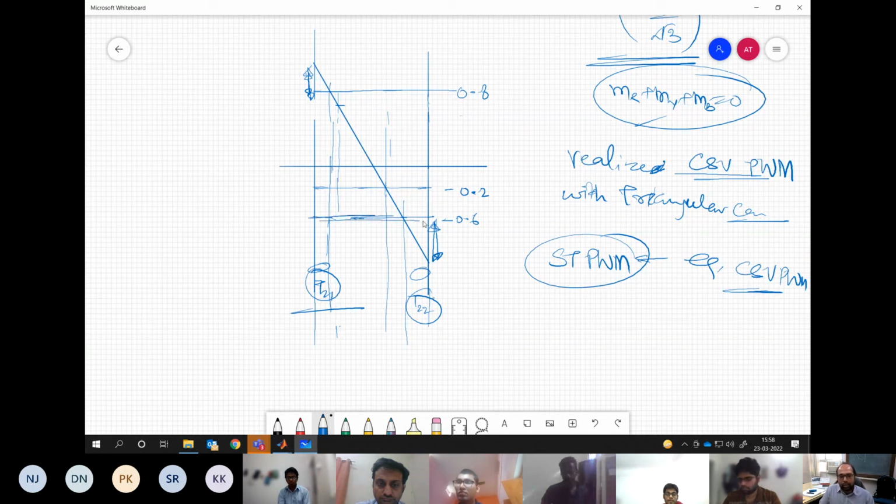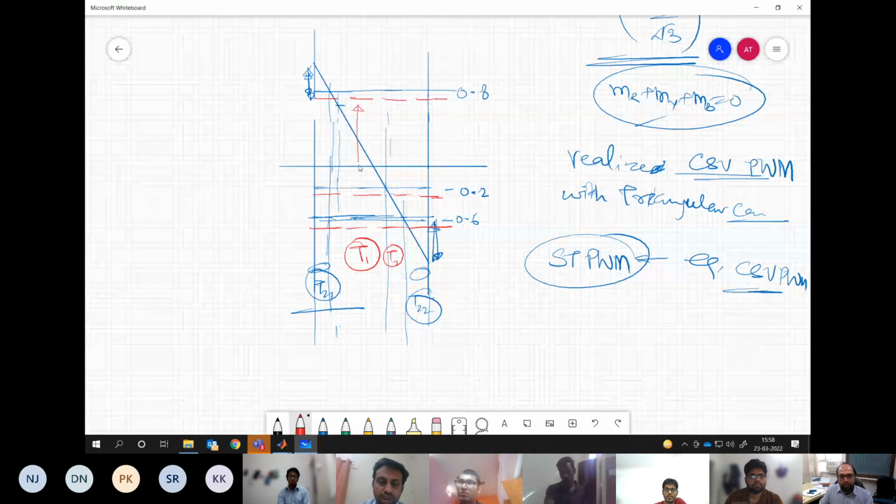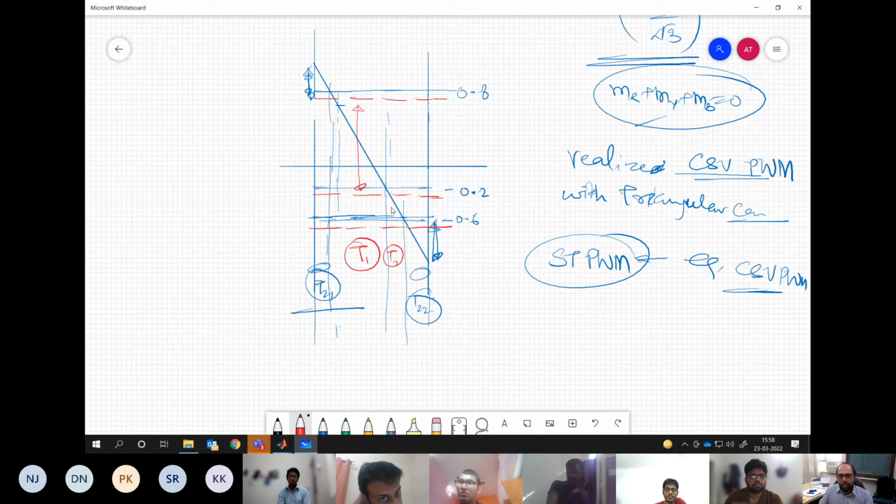Let's say if you shift all three waveforms by a certain amount, say I shift all by equal values. Is it going to change my durations T1 and T2? No, sir, because this difference remains the same, which is responsible for these T1 and T2 dwell times. These gaps are going to remain the same. What will change basically is the value which is now coming over here.